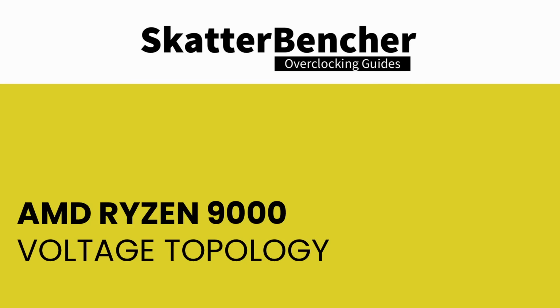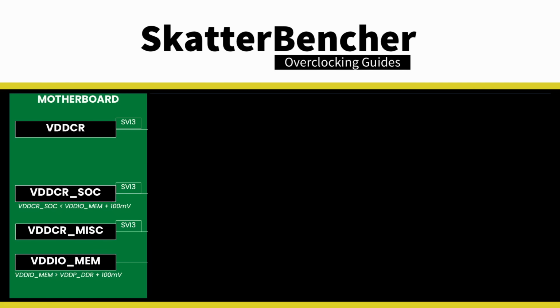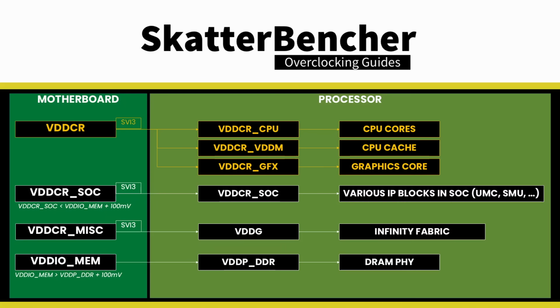The Ryzen 9000 voltage topology relies on a combination of internal and external power supply to generate the processor voltages. There are 4 primary power supplies from the motherboard VRM to the processor. The VDDCR voltage rail provides the external power for 3 internal voltage regulators. VDDCR CPU provides the voltage for the CPU cores in the CCX.